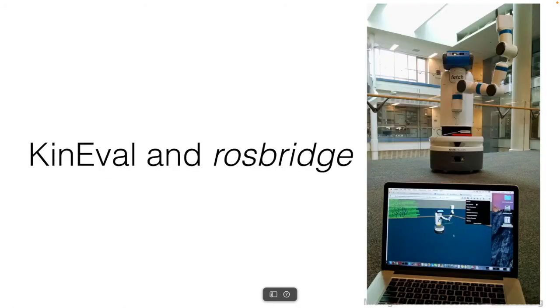But for our class, one place where we are going to use Robot Web Tools, so ROSBridge here is referring to Robot Web Tools, is the optional exercise where you can connect your Kineval stencil to our physical Fetch robot from the Laboratory for Progress. We'll be able to display the real-time joint state of the Fetch within your browser, as shown in this slide. The way we'll do that is by using Robot Web Tools to transfer the joint state information from the Fetch to your browser for the forward kinematics routine built into your Kineval stencil.